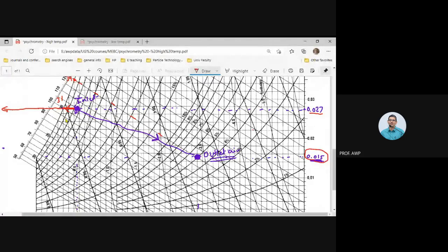So the moment we start going below 30 degrees centigrade, water will start condensing out. Water vapor will convert into liquid water, right? And as we cool to 29, as we cool to 28, 27, 26, 25, some of the water vapor will condense and become liquid water. Humidity will reduce, but the air that is remaining will be 100% saturated. Do you agree with that?